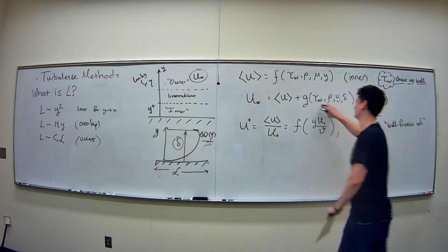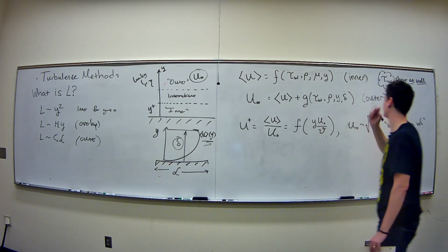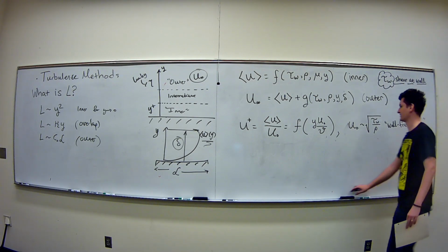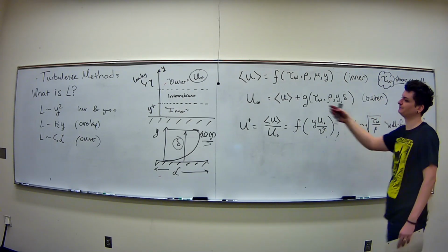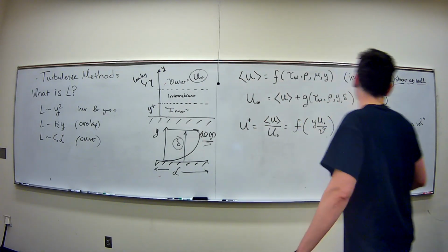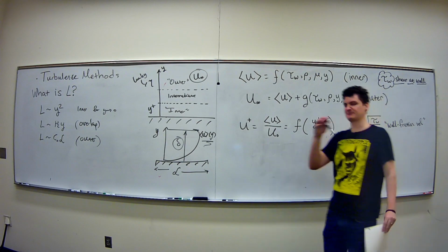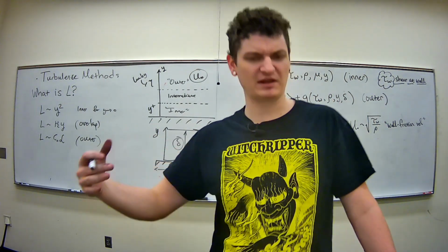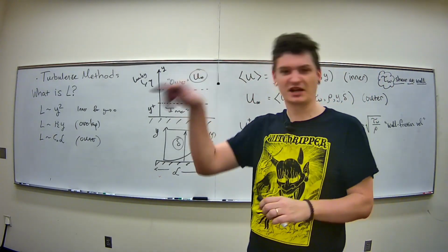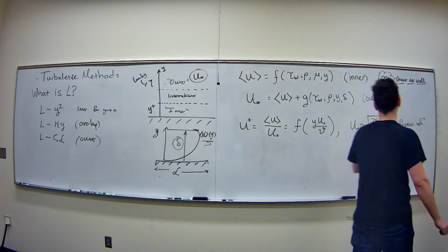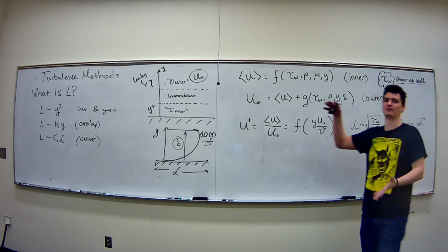Okay, wall friction velocity is a very famous velocity scale, and it comes from many arguments. You can get this idea just from the unit analysis of these functions. Okay, I don't quite like Buckingham pi to do these types of things, so you can also understand this velocity scale being, right, it's not the boundary layer. You know, when you did the speed of diffusion, remember in the vorticity lecture you had this diffusion velocity due to viscous forces. So you had that delta, you did a d delta dt, and you could get something that had a square root in there as well. It's really the same thing happening right here.